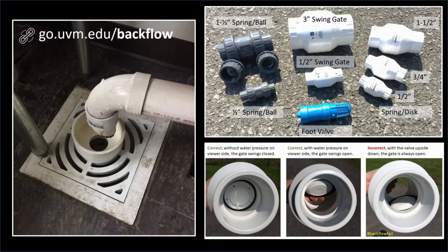And the reason it's broken like that is if there's a blockage downstream of what we're looking at, and there's another discharge that's feeding into that drain, it could overflow that drain, but it would only see the floor. It wouldn't go up, for example, to the sink in the upper portion of that photo. So it's protecting the sink from what other sources might be connected to that common drain.